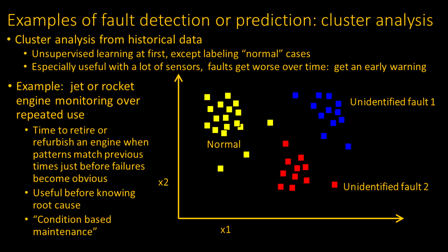Now, some of their failure modes grow over a period of time. For instance, a pebble might chip part of a turbine blade, and this leads to some vibration due to the unbalanced rotation. And that vibration may eventually lead to some other small damage, pieces flying off of the blade, maybe some bearing wear, all of which does more damage, leading to more vibration, and the damage grows over time.